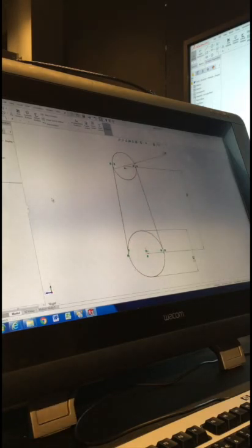So cancel the extrude. Press Escape or press the red cross. Click on the sketch, click Edit Sketch, and on the sketch toolbar, click on the tool that's Trim Entities, the scissors. So the trim tool, there's 5 different options there.